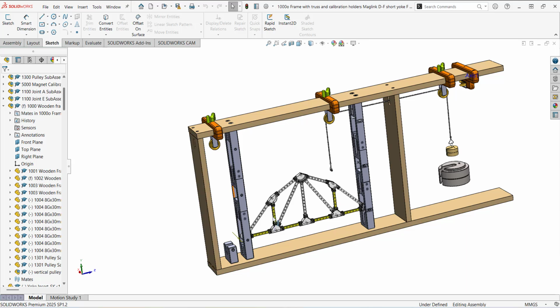On the left hand side, you just mount the collapsible member vertically. One end is fitted here, and the other end you tie the rope. The rope goes through this pulley, through all these slots, coming all the way here where a drop weight would apply the load, and you gradually increase this until the magnet is broken.